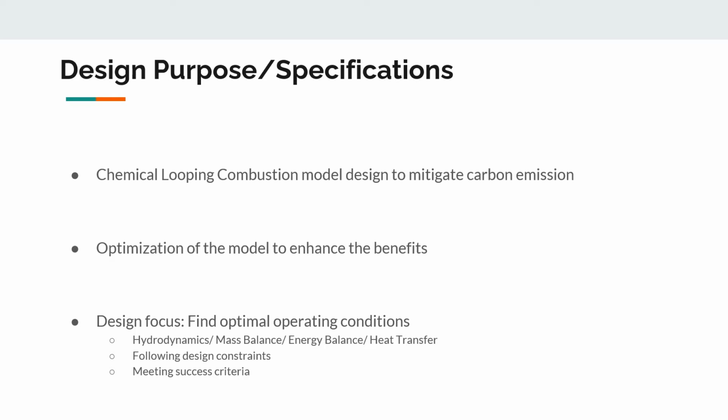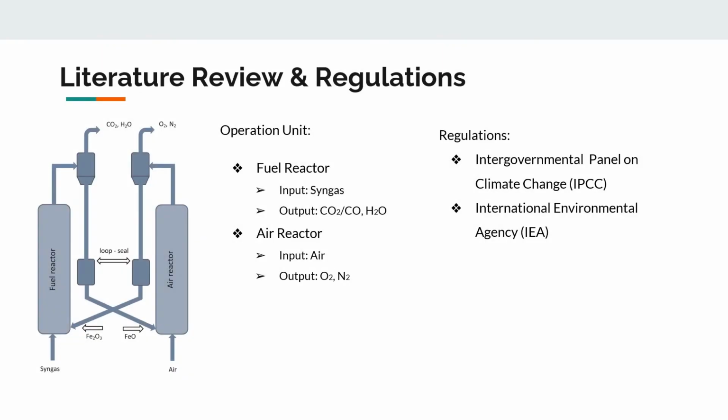Essentially, it is our aim to minimize the operational and capital cost of the process, followed by the decision matrix explained later. The published papers from various institutes have provided us a general understanding of chemical looping combustion. It involves an indirect combustion through oxidizing a metal to combust the fuel gas. In our case, ilmenite has been chosen as an oxygen carrier.